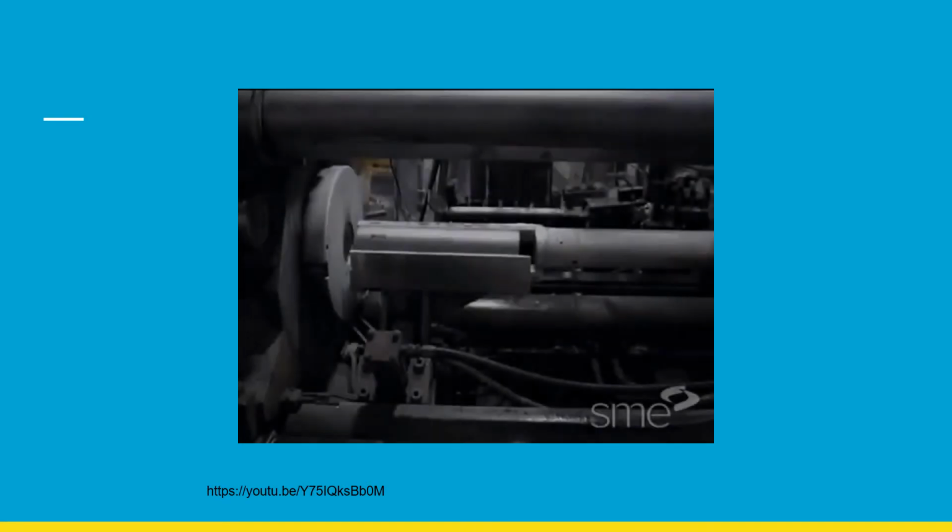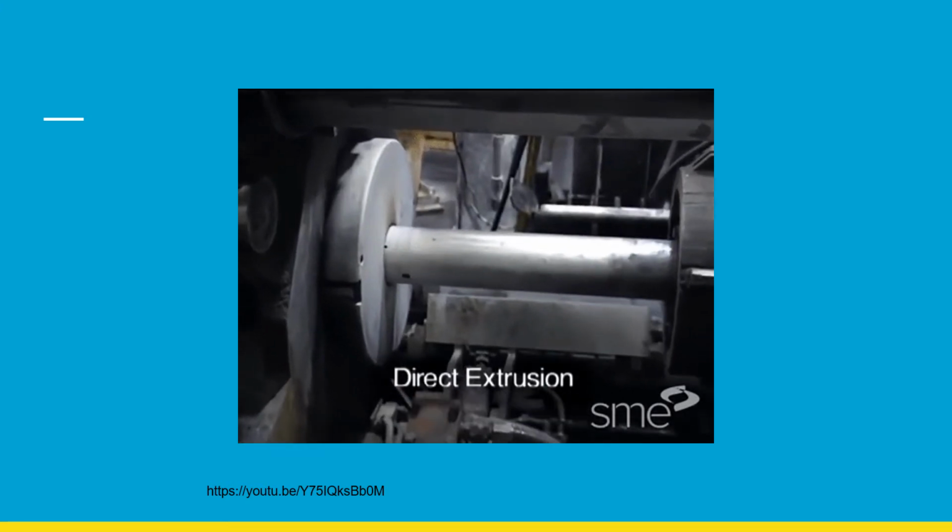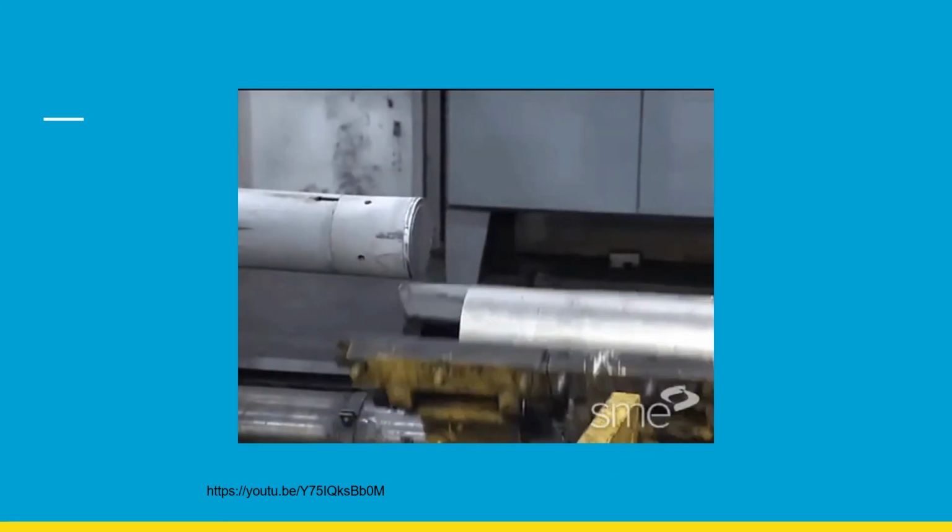Direct extrusion works by placing the billet in a heavily walled container. The billet is then pushed through the die by the ram or screw. There is a reusable dummy block between the ram and the billet to keep them separated.